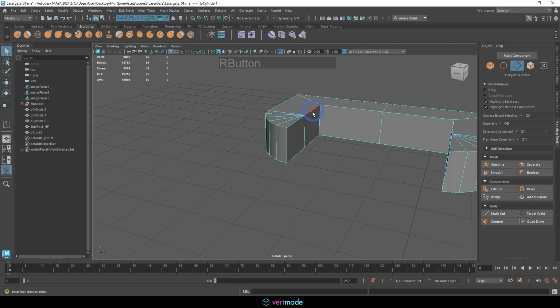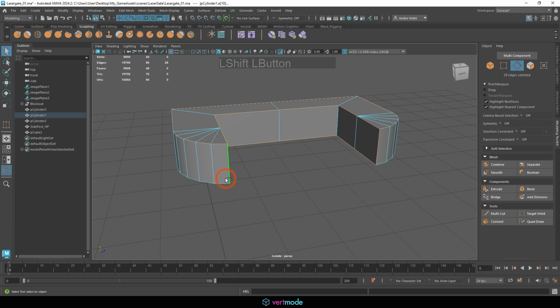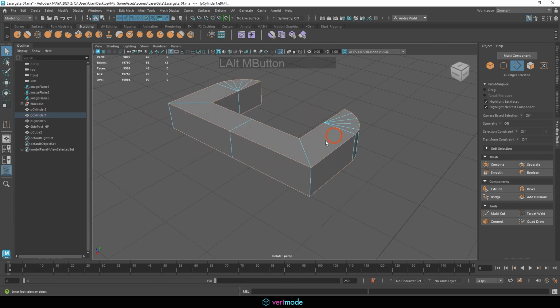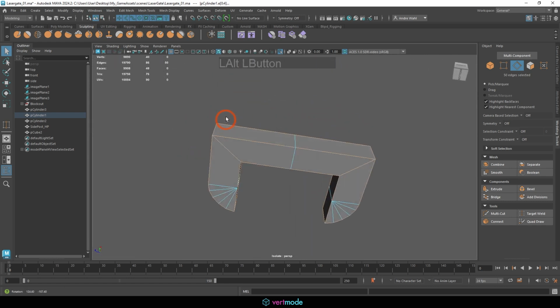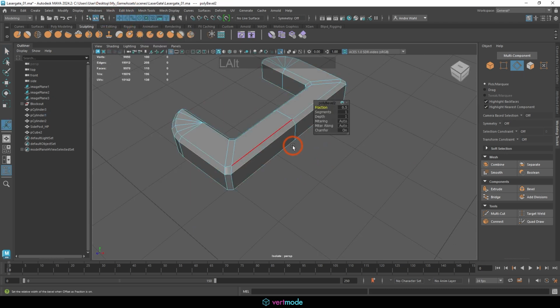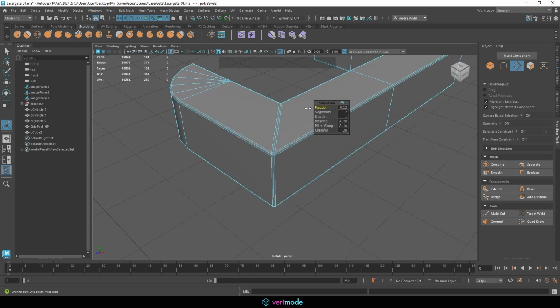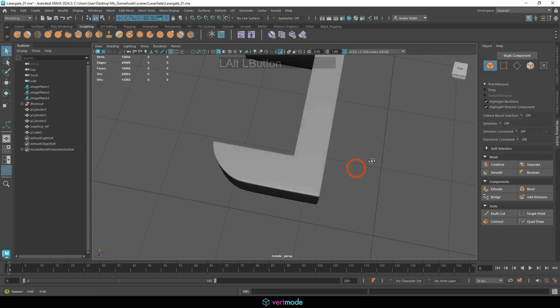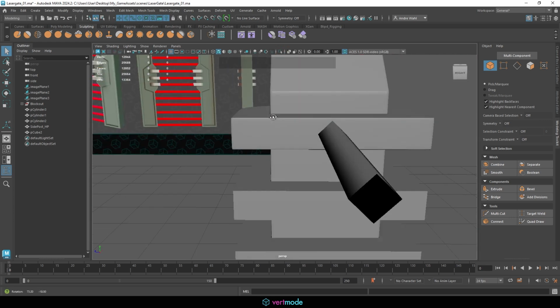So in this instance, I'm going to go into edge mode. I'm just going to double-click the edges that I want to have in their entirety here, which are going to be our border edges running around the outside, tops and bottoms, and then the round area we don't want to touch, but these corners we're going to want to get a nice bevel to. And that's pretty much going to do the trick. So once we have all the edges we like selected, we can just come up here to Edit Mesh Bevel, segments to 2, and give it a nice tight amount of segments here. So when we press 3, we get this beautiful end result that smooths out nicely and gives us those bevel edges, which is mainly what we're going for in the bake.